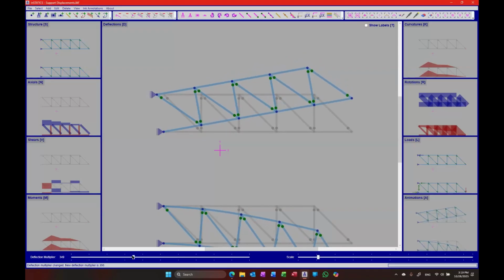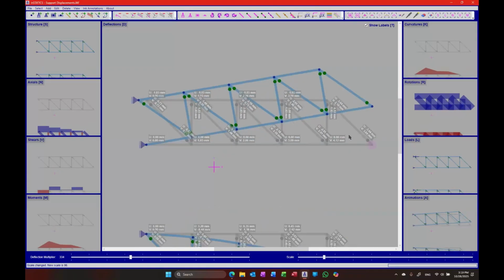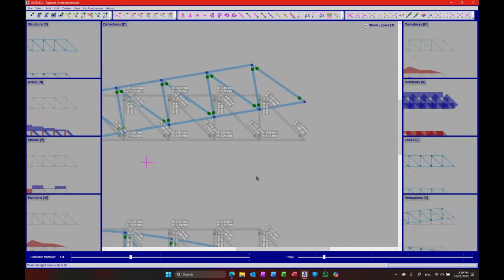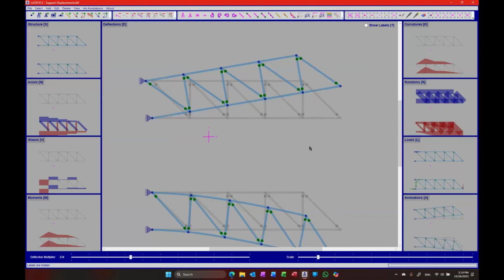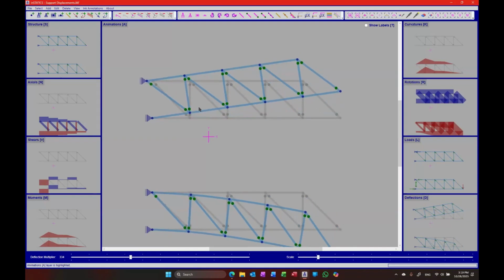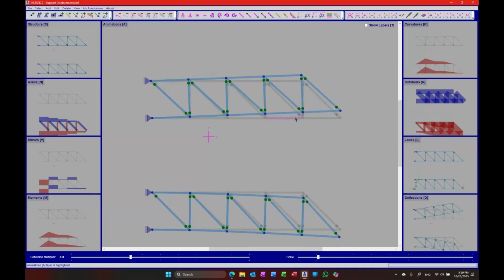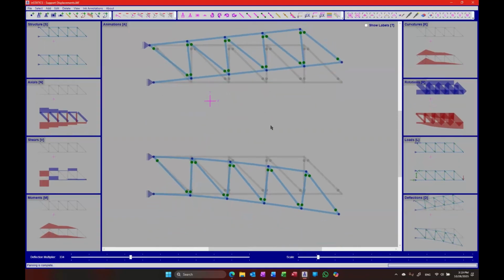Let's take a look at the values a little bit. This one's 1.03. This one moves about 5.15. It's exactly 5 times, because we have the small deformations assumption, right? So why am I showing you this? I want you to see how structures will behave, even if it is almost determinate like this structure, when their supports are actually deforming.